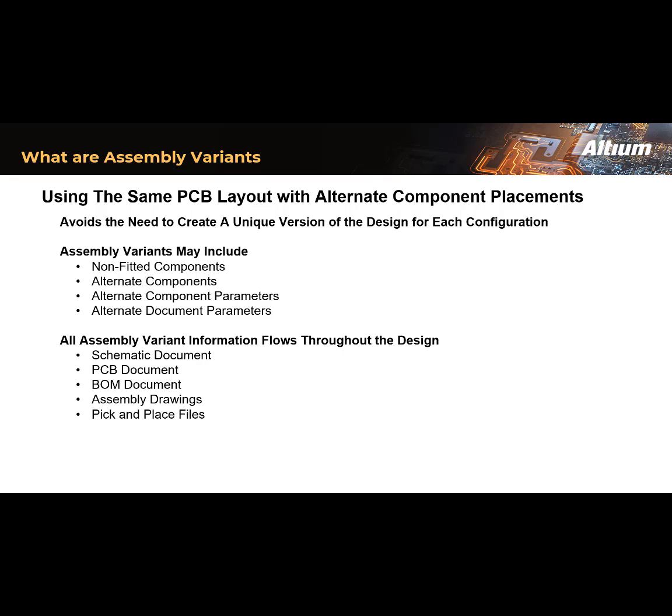So you can rename the schematics to indicate what the variant is and so on, and I'll show you how that works. Design variants that use any of these types of variations to the assembly are referred to as assembly variants, as they only impact the assembly process. In this case, all variants will share the same PCB fab at the end of the day.